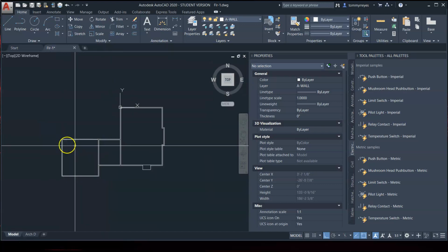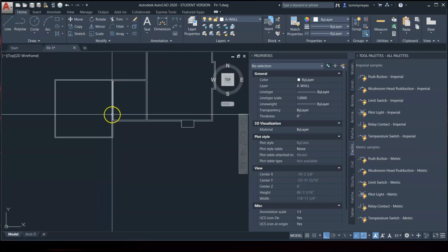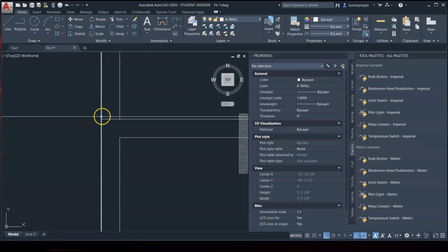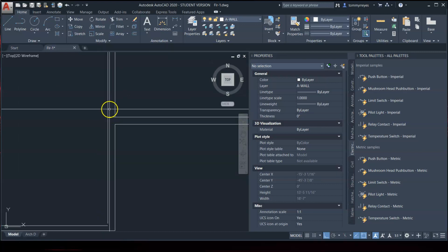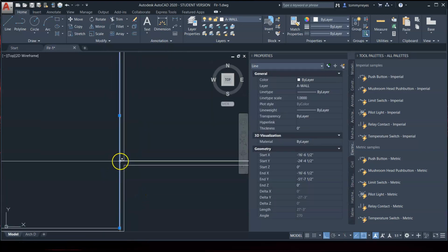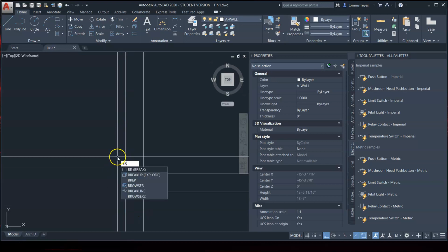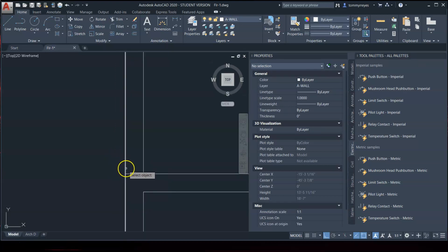And I'm cleaning as I go because I don't want to forget. And this part right here, I know the book doesn't tell you about a particular command that I find very useful for situations like this, where you have one solid line, but you need to move just this portion over 2 inches. And so this is a great command. Break, BR, spacebar. And I just like to break it close to here and then use the fillet command.